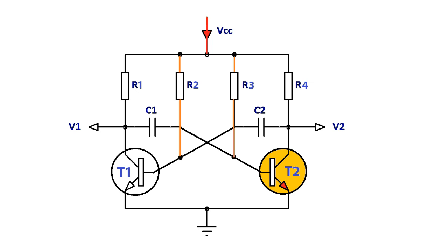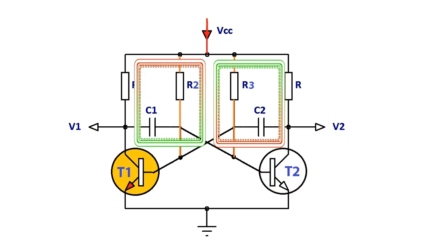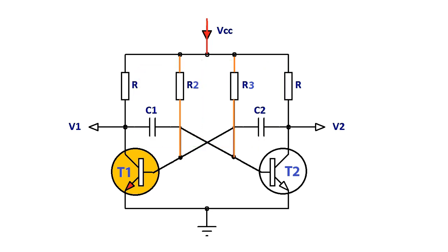This action starts the whole process over again, but now with capacitor C2 taking the base of transistor TR1 to negative 5.4 volts, while charging up via resistor R2 and entering the second unstable state. Then we can see that the circuit alternates between one unstable state in which transistor T1 is off and transistor T2 is on, and a second unstable state in which T1 is on and T2 is off, at a rate determined by the RC values. This process will repeat itself over and over again as long as the supply voltage is present.